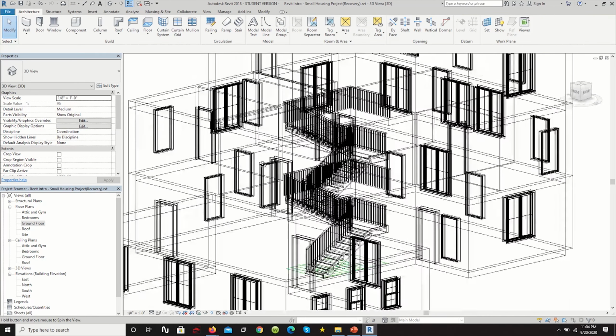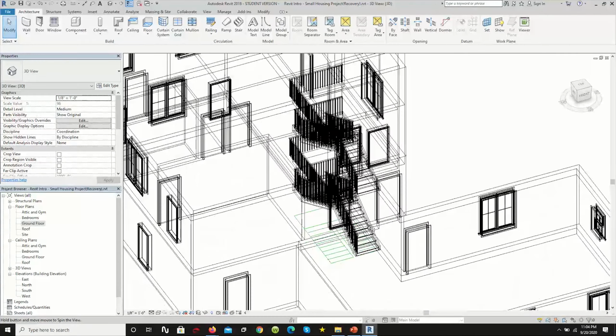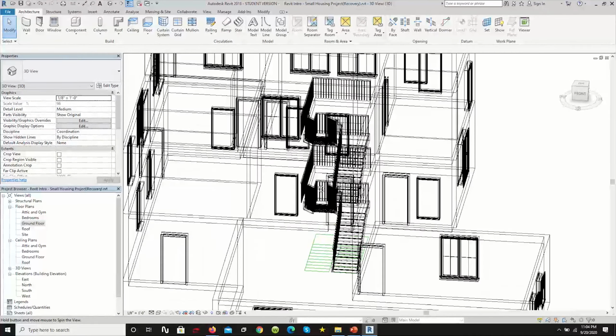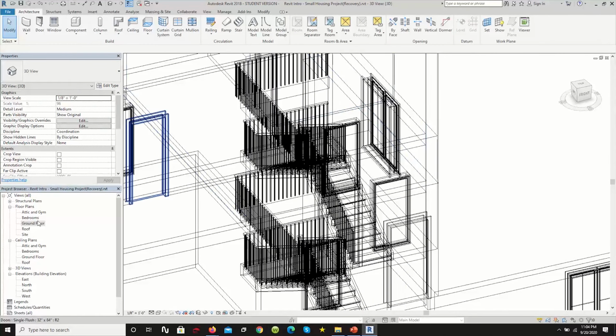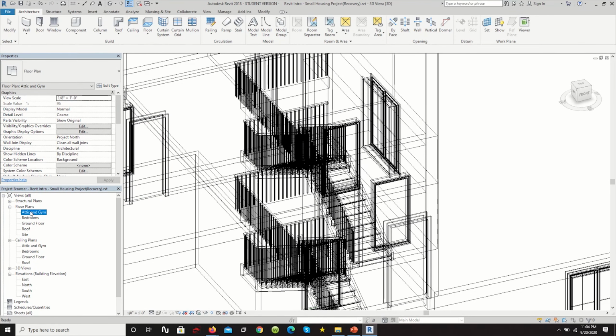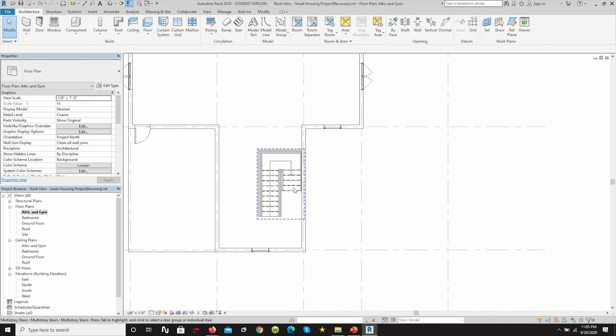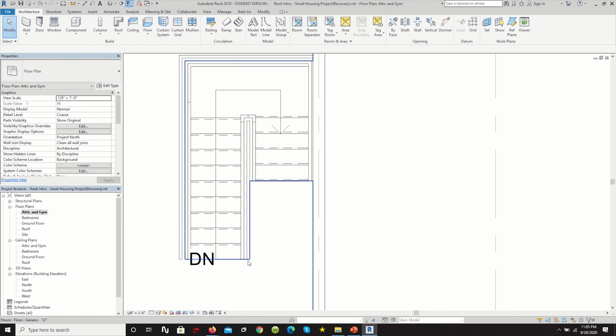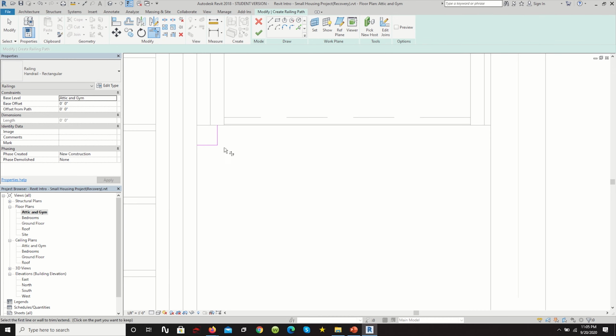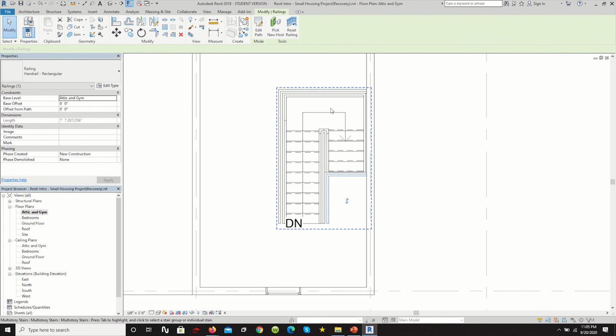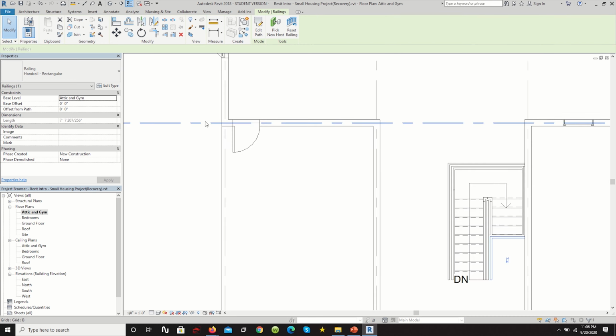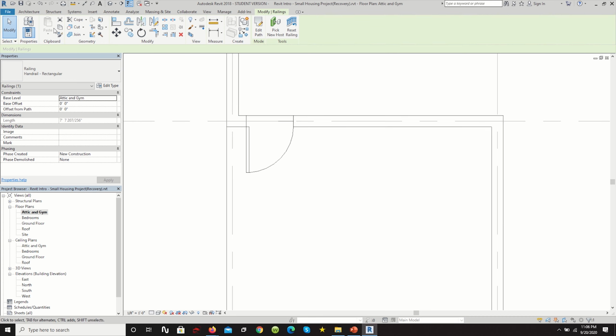3D view. And now once you have each of those things drawn and you have your floor outlined, oops, I missed one area right there. Let's do that. For the attic and gym, we have to have a railing here because there isn't another staircase that continues upwards. So let's do that quickly. We have our generic railing baluster. And we also want to apply this outside as well. So let's do the same thing outside.